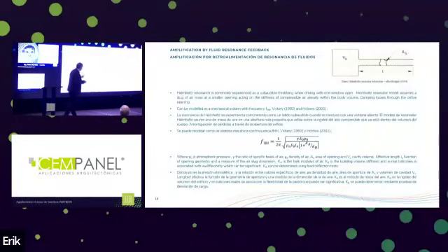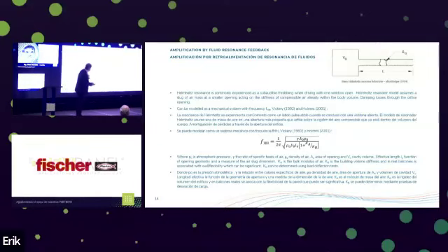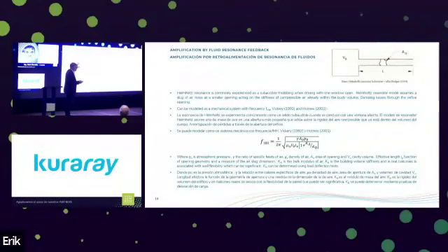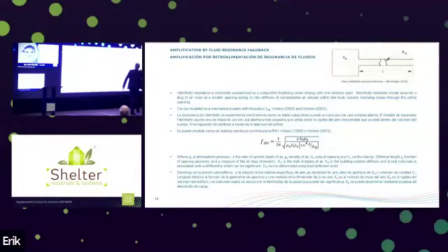Now, another excitation mechanism is Helmholtz resonance. Helmholtz resonance is commonly experienced as a subaudible throbbing. When driving in a car with one window open, you've probably experienced having the window down a little bit at high speed and you feel it. That's a Helmholtz resonance. And it can be modeled with this resonator model, assuming a slug of air mass acting on the stiffness of the enclosed volume with some damping losses through the opening orifice.